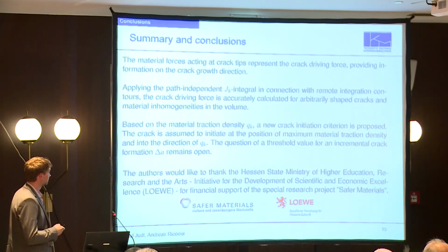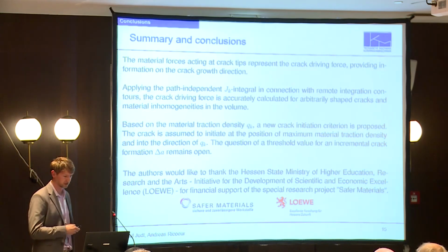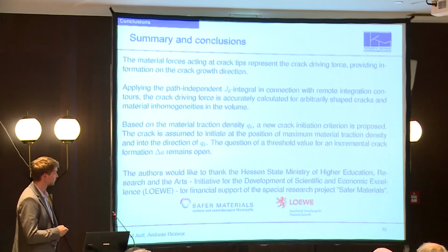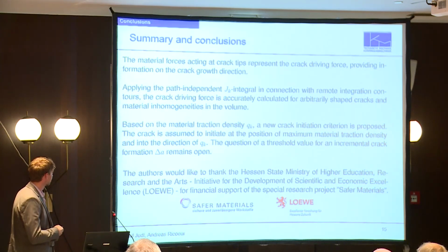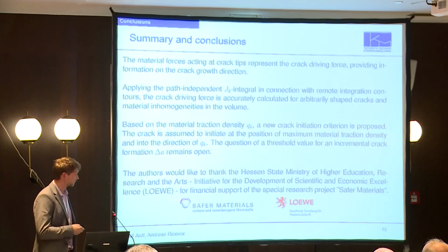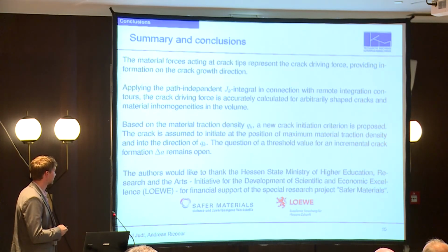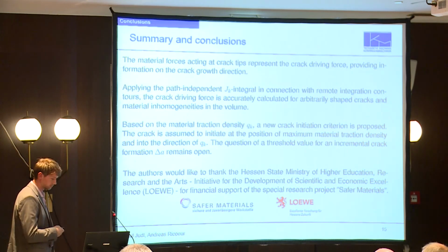Furthermore, we applied the path-independent integral to calculate accurately the loading quantities at cracks of arbitrary shape, and also material inhomogeneities in the volume. Fourth, I presented an approach for finding the position and direction of crack initiation, applying this material forces approach.